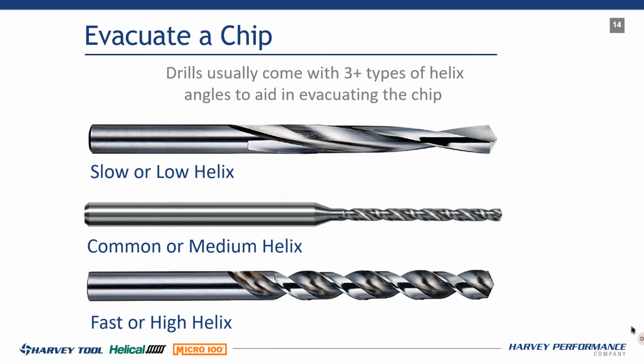Then you've got carbide tip drills. Well, the helix angle is designed to manage certain types of chips. So we've got 3 different helix angles that you're going to see as standard. There's more than this, but they break down to a standard overview.